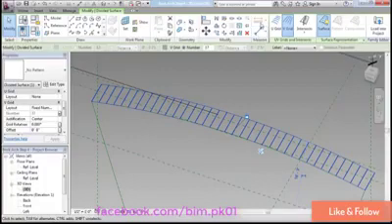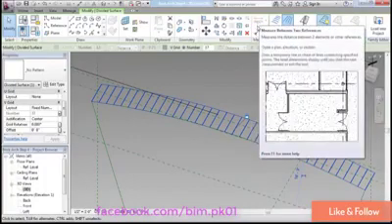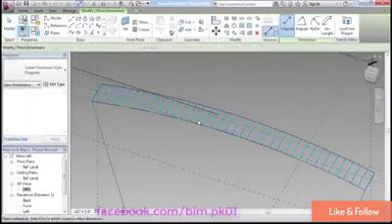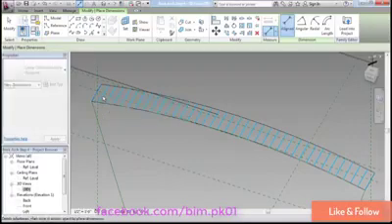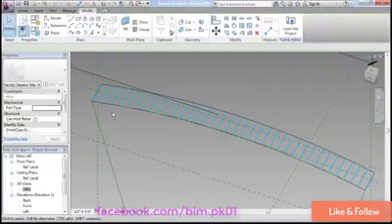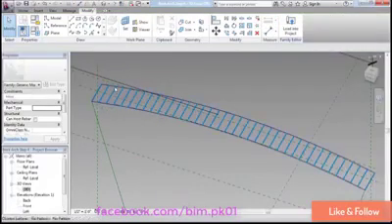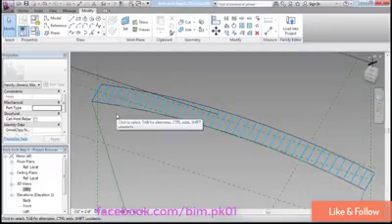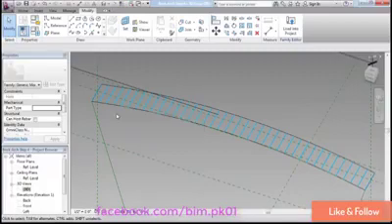If you were to actually measure those, you would find that that's 1/3 of that 8-inch dimension, more or less. It's a little plus or minus because, as we talked about, we're rounding the value up. But that's roughly 1/3 of 8 inches or brick size. So we're using that number in there for the width of the brick, and we've got the 8 inches back here. And so that means that the height that we want here is about 4 inches, 3 5/8, because we're essentially setting up a row lock situation here. So in the next movie, we're actually going to go in and apply some geometry along there to represent the bricks and start seeing how the arch is shaping up.